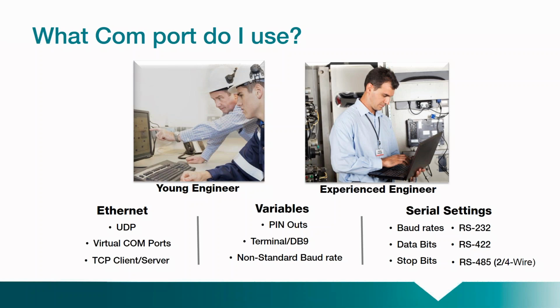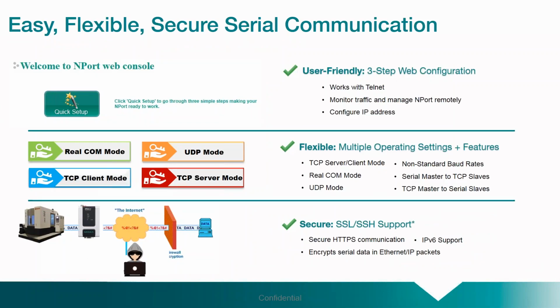or how to run the cabling for a terminal versus a DB9, or non-standard baud rates, right? Or maybe the serial settings. You have things like data bits, stop bits. Is it RS-232? Is it 422, 485? Those are all really important considerations.